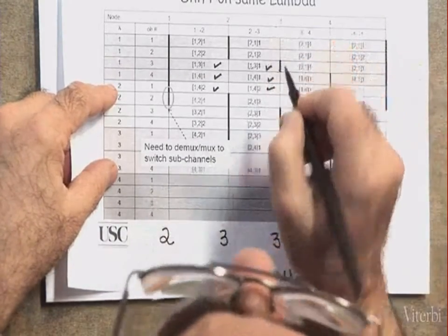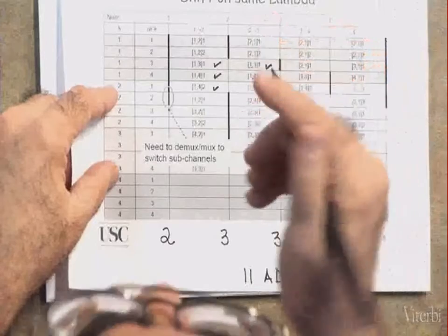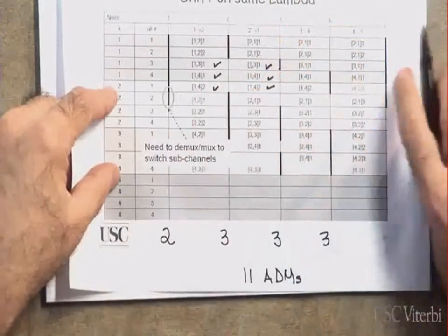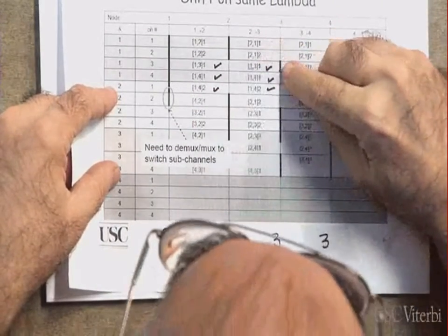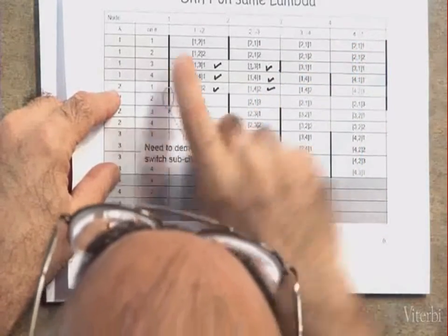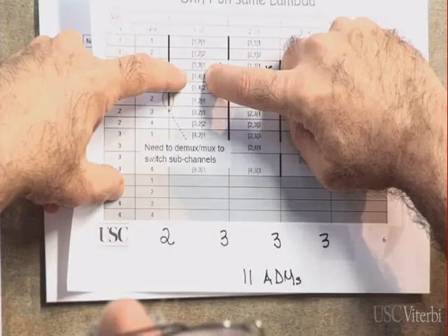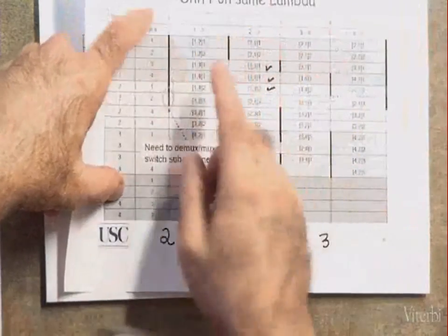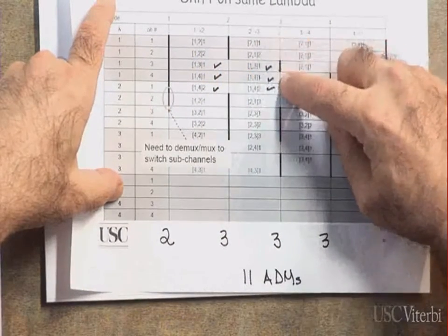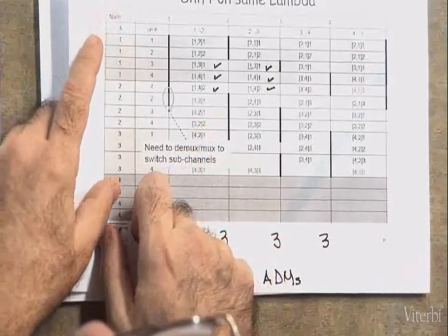In here at node 3, do we need an added drop mux? Here. Do we need an added drop mux? For which channel? For the one that is originating at 1 and terminating at 3. Only for that. Can I move this one to wavelength number 2, and move the 141 to take its place, and 142 to take the place of 141, such that on wavelength 1, there is no termination at node 3, which means I eliminated this guy. Yes or no?